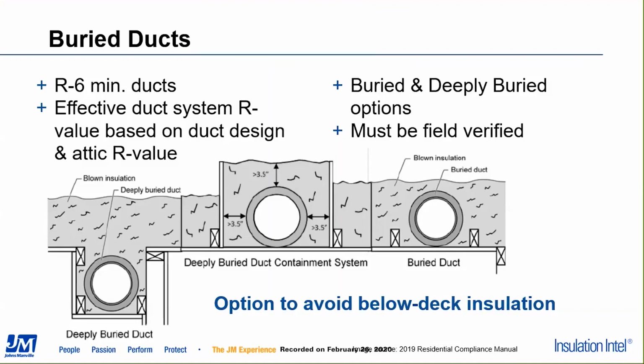To achieve this, the ductwork is buried under at least 3.5 inches of insulation. That's what's called a deeply buried duct, and a deeply buried duct is effectively counted as being in conditioned space.